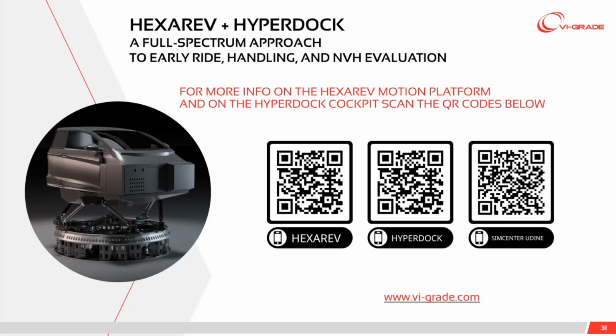This is a fairly long question. Someone is asking, will it be possible to separate the sources of vibrations to include the contribution of subsystems such as the drivetrain, in a way that the chassis and NVH teams can work on tuning the drivetrain mounts to arrive at a compromise for ride comfort and isolation? Again, the short answer is yes. Basically, that all depends on how you tie the vehicle model with the NVH simulator. So in our full spectrum approach, there are different possibilities.